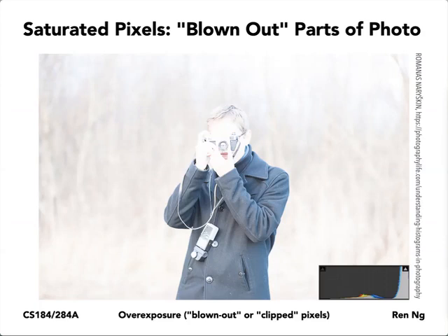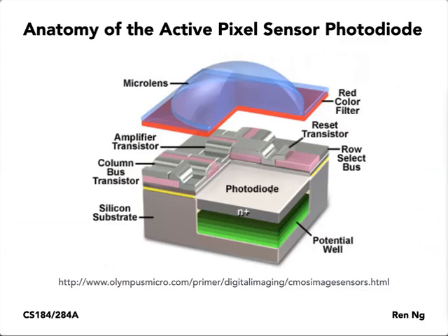So remember in the architecture of a 3D pixel, let me just go back to that picture for a moment to remind you what it looks like. This is a three-dimensional physical structure, right? And the exposed part here of the silicon surface called the photodiode is where the photoelectric effect is happening. And then there's a physical structure in here that's set off with semiconductor processing to create electric field locally to pin those electrons inside a potential well. This is a real 3D structure, so you can't fill it with an arbitrary number of electrons, right?